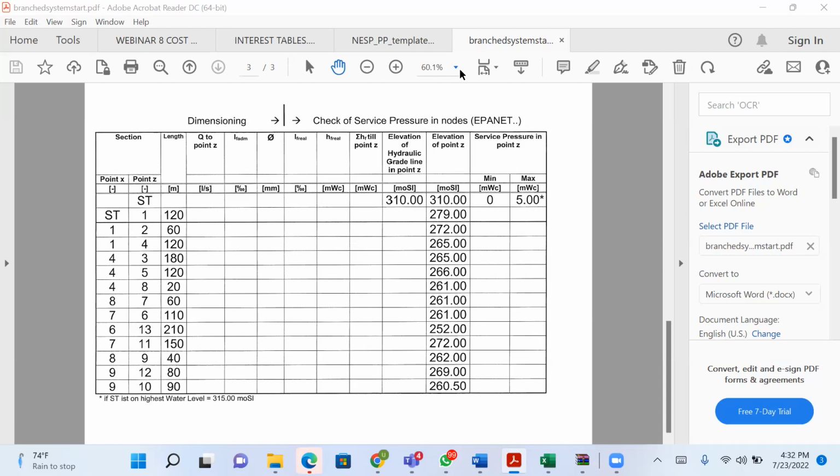So for you to get a pipe size, you must first get the discharge. So that's the trick. As soon as you get these 4 parameters, you are done with the design. The next thing you need to do is go to your AutoCAD map and then detail it. But the calculation sheet will be done in this format. So take cognizance of this format because it's very, very important.